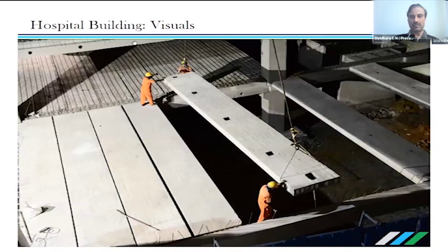Even in this slab, you can see so many openings. These are, suppose, the toilet area, and floor traps and all are required. That is all implemented in the production itself. When we erect the slab, all these MEP requirements are in place. In the normal case, they will always chip and damage the slabs. That can all be avoided in precast, because these predefined openings are made at the factory itself as per the MEP consultant's requirement.